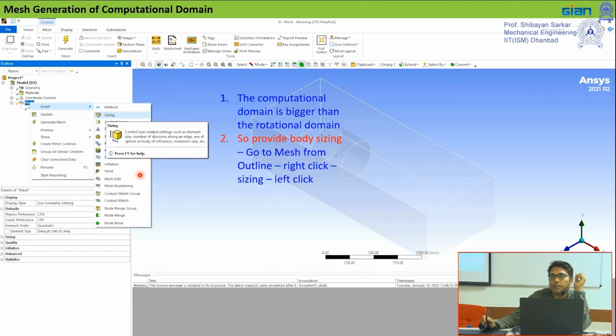If you remember the performance curve with different TSR, you will be calculating different CP values, then only you will be able to produce a performance curve, and that particular performance curve will correspond to a particular river flow condition. Now if you change your river flow condition, that means the same set will be for different other conditions. Now if you modify the river construction, so some changes in the river geometry, then again you have to change all these exercises.